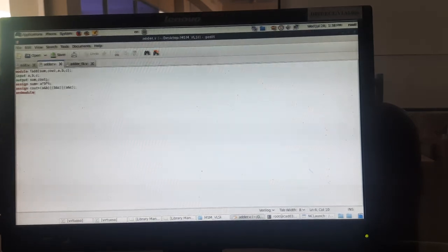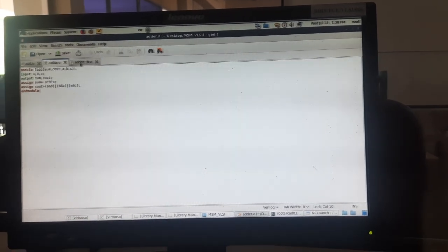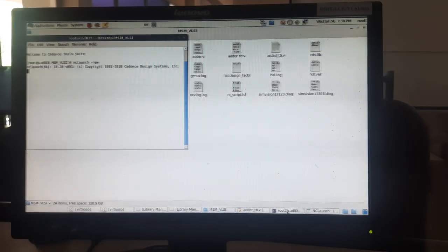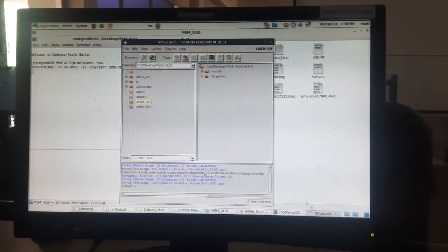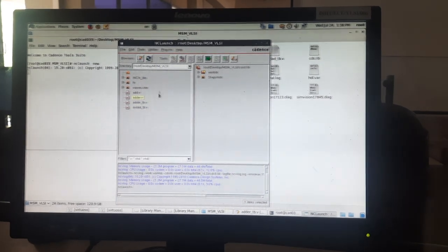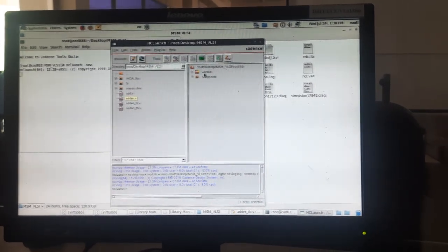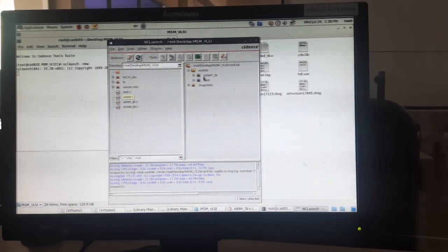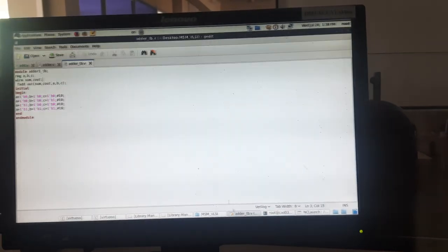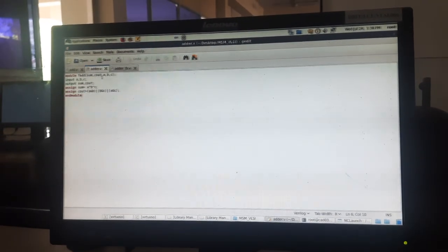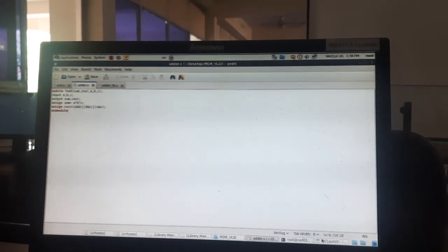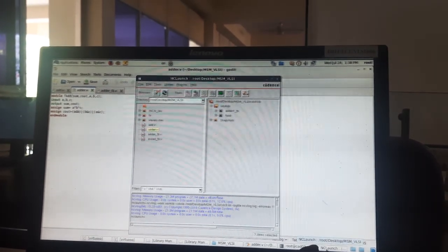So I'll show you that. So these are the codes that we typed and these are the files. So those files exist here. Those same files. So we launched Cadence, and in the nc launch window we compile them. Once done, we need to go to this section, work lib plus icon. So we'll have our two modules here. These are the adder1_tb module inside the test bench file, and full adder module inside the adder.v file. So in the nc launch window, bottom task, we can find that always.